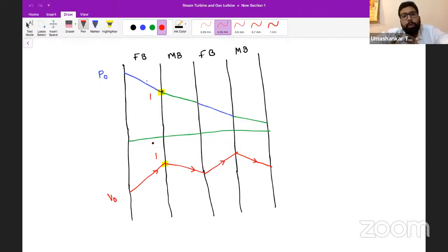Now as the steam flows through the moving blade, this pressure energy will reduce and will give you a difference of relative velocity, which will help the impulsive effect even more, and the blade will rotate with even higher speed. Most of this is explained in the first session also.